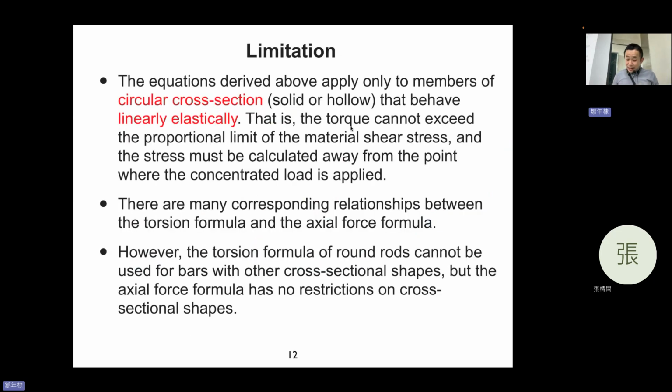Limitation. The equations derived above are only applied for circular cross-section, because you saw R and IP, they are all focusing on circular cross-section. And linearly elastic, Hooke's law. You can notice that there are many corresponding relationships between the torsion formula and the axial force formula. I believe you agree with that.